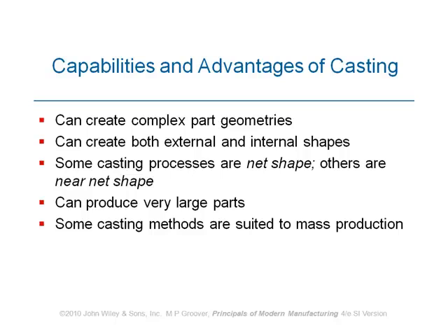So there is significantly lower time which is needed in order to make the part by making use of this process. The other thing is that we can make internal and external shapes in the part by making use of casting. What does this mean? It means that any part has an external shape, how it looks like from outside. What happens if there is a hole or another shape or cavity inside the part? It is still possible to make use of, say, some cores in order to make the holes and internal shapes in a cast part.